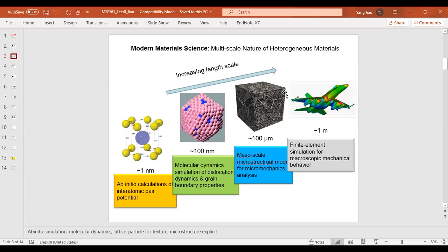Okay, so this is the simulated microstructure of a titanium alloy, and you can see that they have some primary alpha grains, these large polyhedral things, and very small anisotropic beta grains that come from the solid-solid phase transformation. So the microstructure of this, like the size of the grain, how they're oriented in this microstructure, they're all going to play a role in determining the mechanical properties.